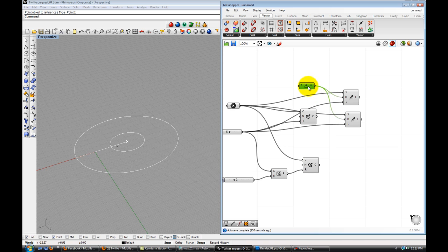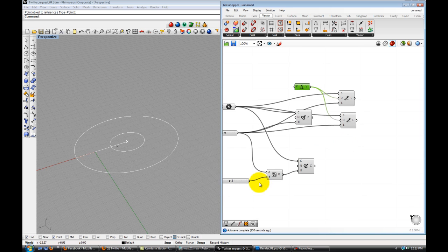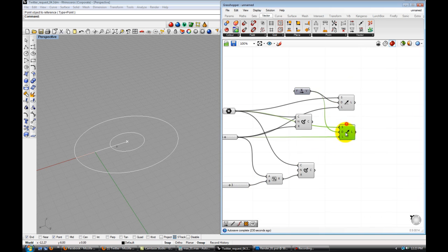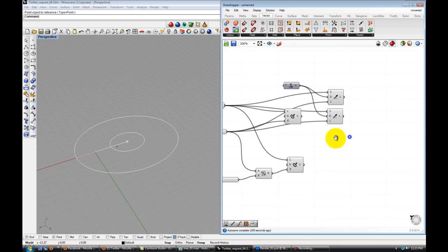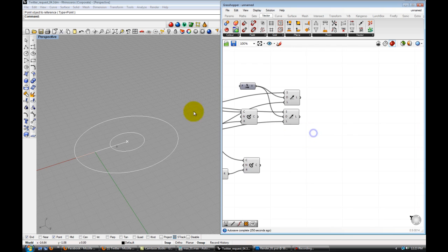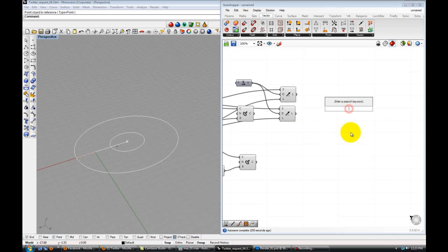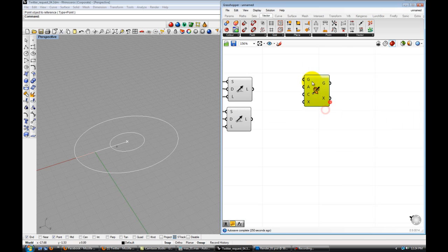And we want to create two of those lines. So vector x stays, this is direction 1, and the center line stays, as well as the radius. So we're basically duplicating the same line twice. Next, we want to be able to rotate those lines, move them around the perimeter. So I'm going to drop in a rotate 3D component, and we're going to need 2 of those.